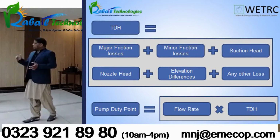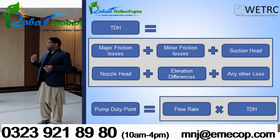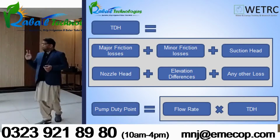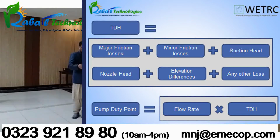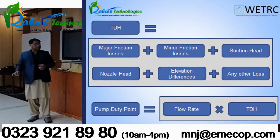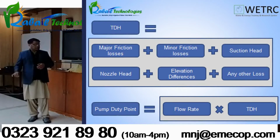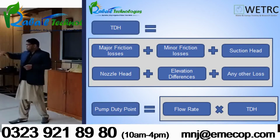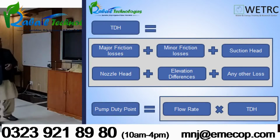And whenever there is flow, it will meet resistance from the pipe. So that is what we call head loss or friction loss. So that is the basic difference between the TDH and static head: the friction losses. So TDH is major friction losses using the Hazen-Williams formula, minor friction losses, which we will discuss later on, suction head, nozzle head, elevation differences or any other loss due to elevation or some other physical structure within the system. So it is called TDH.